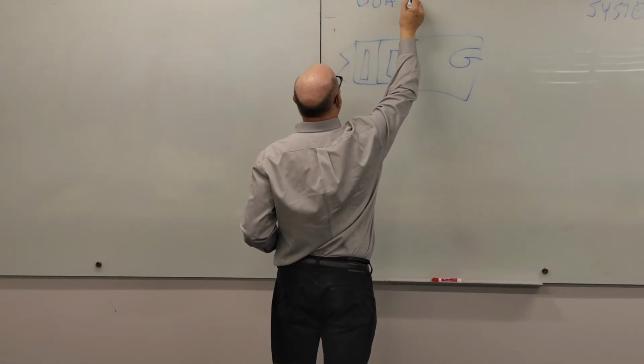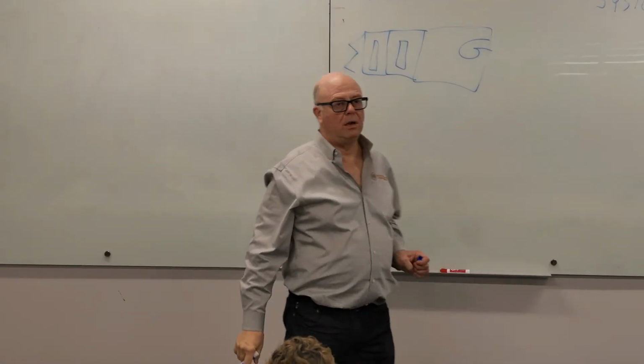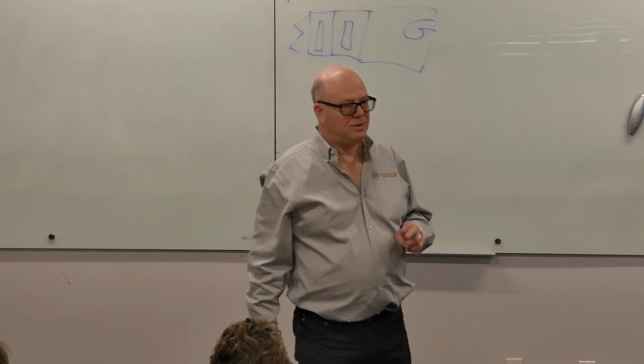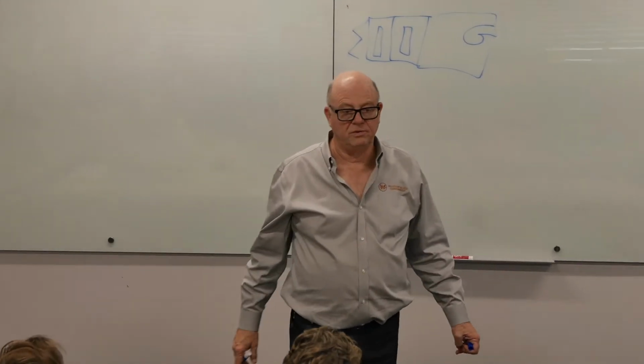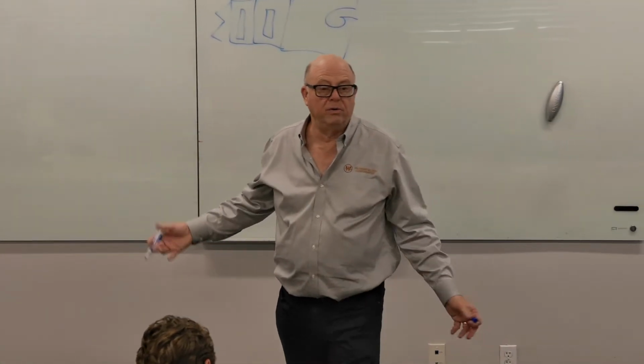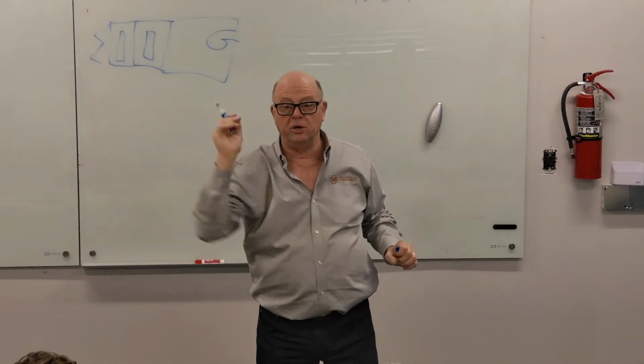What does that stand for? Dedicated outside air system. Yes. This is a little air handler on the roof. Well, it wouldn't have to be little. If it's a big building, it might be a big air handler on the roof. But it's an air handler on the roof that handles 100% outside air.